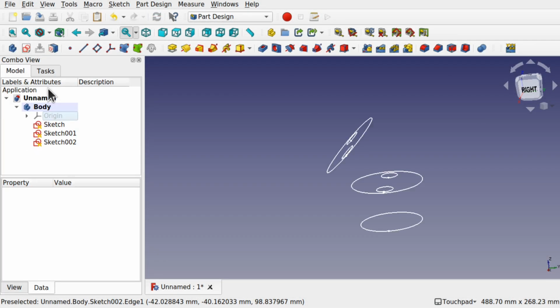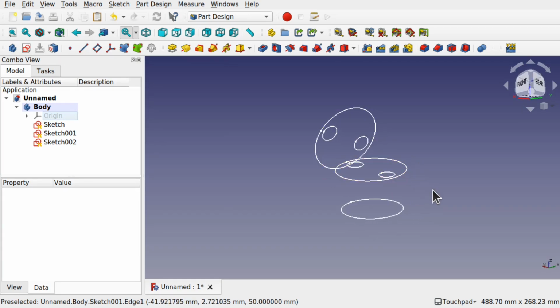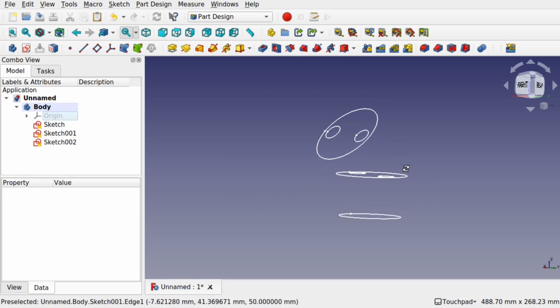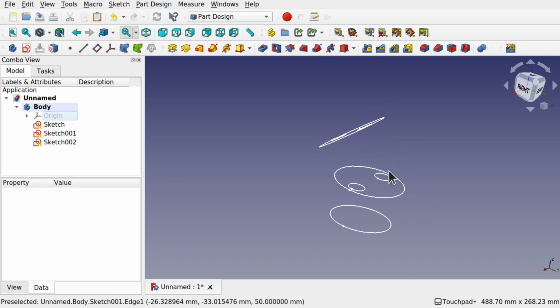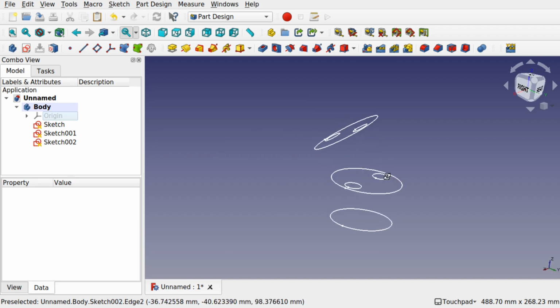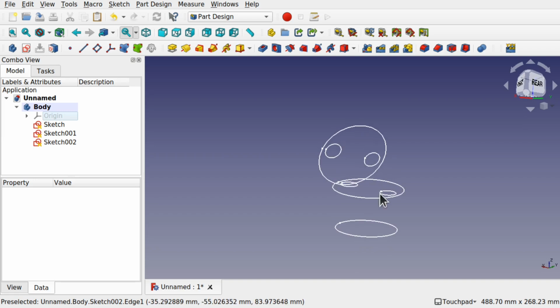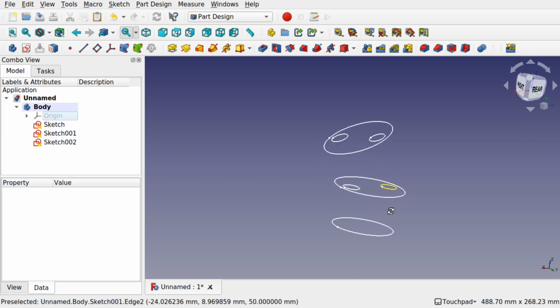If we have this shape and we wanted to loft to here or to loft to a number of profiles, and then the last one we need to loft through to basically holes all the way through there. There is a number of options. You can pad this if you so desire, or what we can do is create a loft first and then use the face.